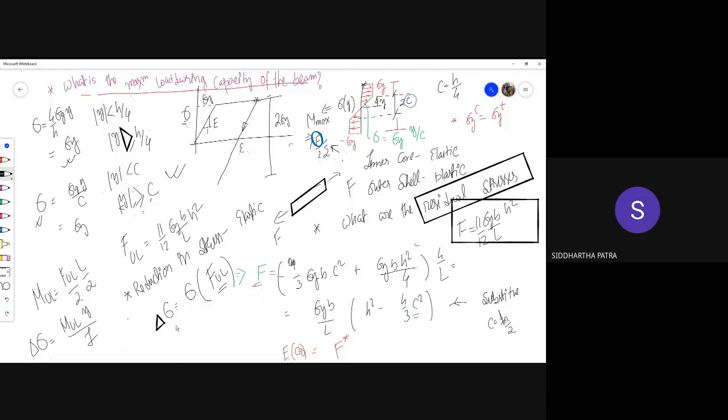Okay, so the second part of the analysis, you started with certain initial set of stresses. When you are over here before unloading, you started with certain initial state of stresses. And then this process is simply elastic and linear. So you can do some linear superposition. Basically, the stress you can directly subtract. So you can consider just one linear operation is happening, and that stress you are simply subtracting.